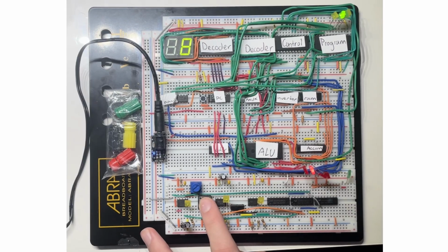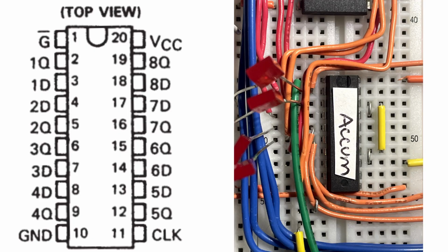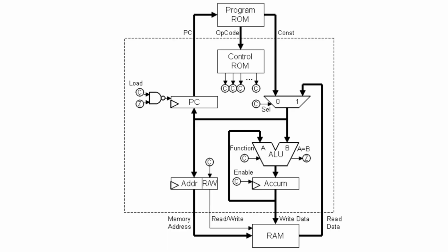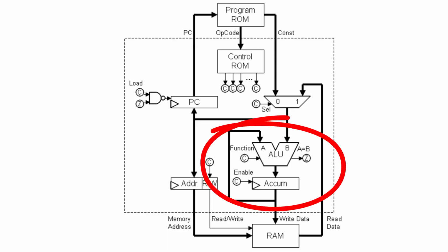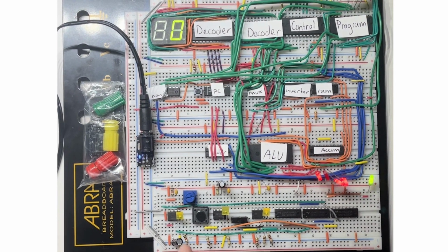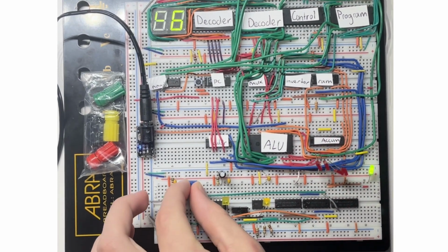The processing pipeline centers around the 74LS377 accumulator. The octal register stores the ALU output and becomes a source of future calculations. Its outputs feed directly back into the ALU 8 inputs, forming a closed computational loop. By enabling the accumulator only when required, the CHUMP cleanly sequences multi-step operations such as arithmetic, comparisons, and branching.